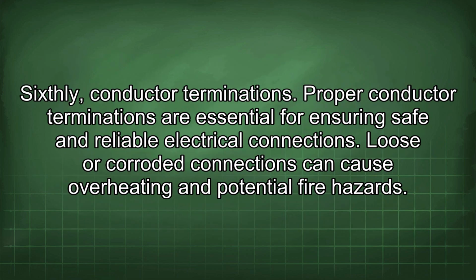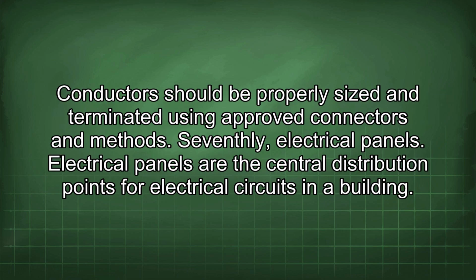Sixthly, conductor terminations. Proper conductor terminations are essential for ensuring safe and reliable electrical connections. Loose or corroded connections can cause overheating and potential fire hazards. Conductors should be properly sized and terminated using approved connectors and methods.